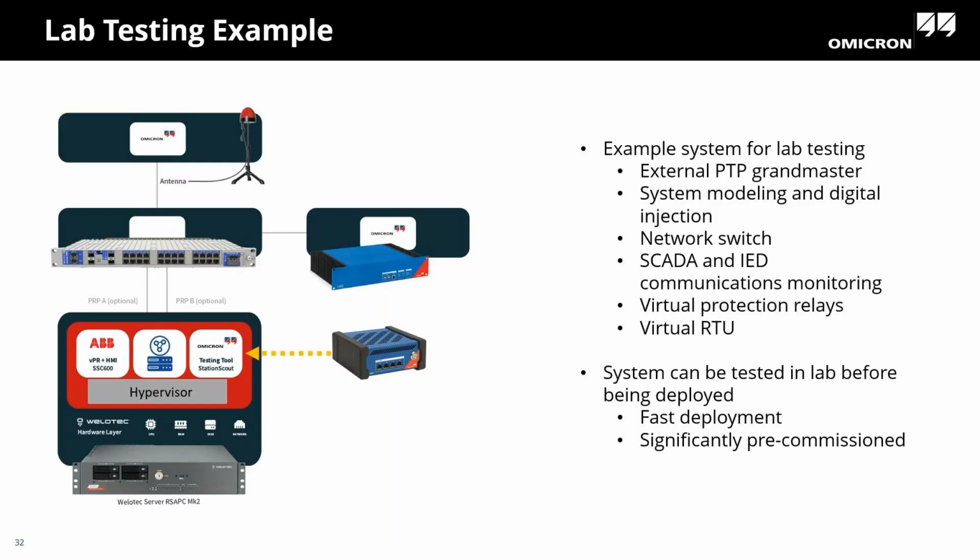Sure, you're still going to have to recommission or do your final commissioning, but it's much better to find any problems early on in the design phase rather than once you're out in the field and it's very difficult to fix. So this I can see as being the real benefit here in terms of testing, is once you have virtual IEDs, you can actually test your exact system before deployment. But then also you can redeploy and copy and paste very, very easily. So there are very nice features that are going to come with virtualization, and all of that virtualization is really enabled by our digitization. So we need those digital protection signals to really enable a lot of this cool technology.